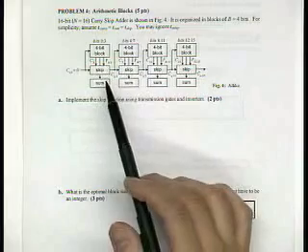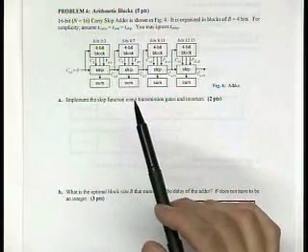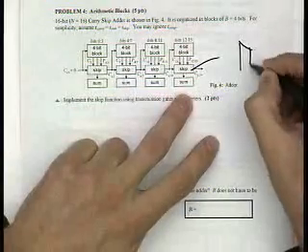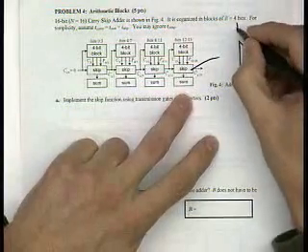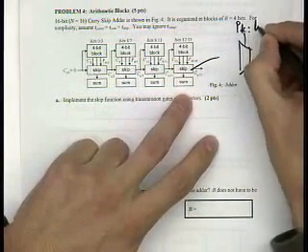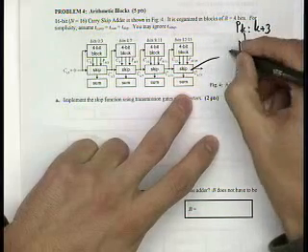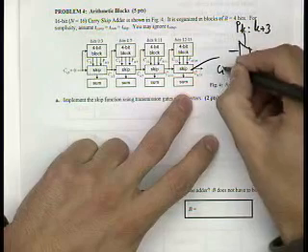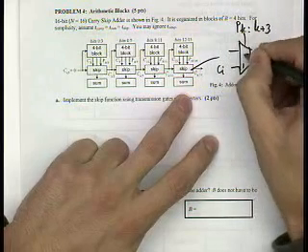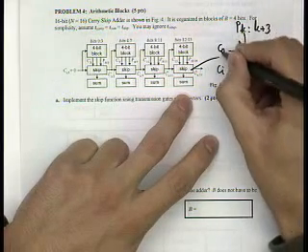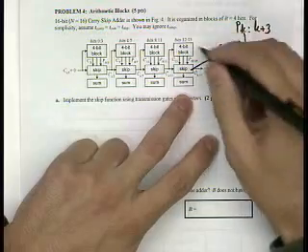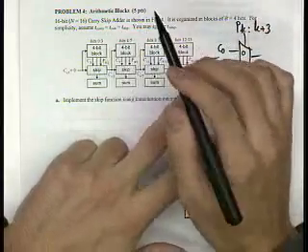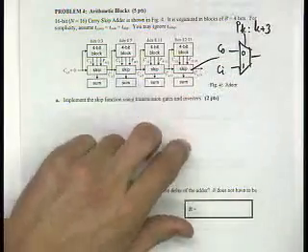The skip function is a simple multiplexer, nothing else. You have the signal P, K to K plus 3. If that is equal to 1, you take the incoming carry, or if it is equal to 0, you take the carry generated from this 4-bit block stage where you have all the rippling.